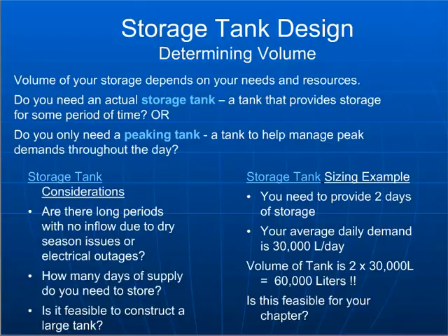So just a quick example of a storage tank: if you've got 300 people using 100 liters of water per day, and you are simply trying to store water for 2 days to make it through whatever situation's causing that outage, then you're going to need a storage tank of about 60,000 liters, which is no small feat to accomplish.